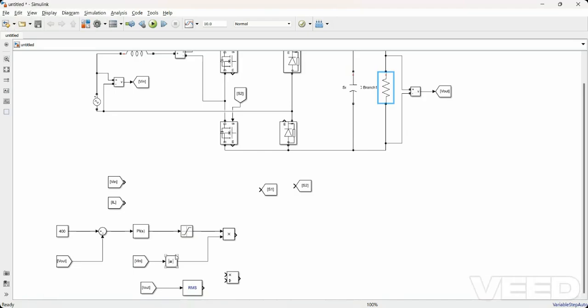So now it is important to have the volt ampere balance, as you can call it. VAC in multiplied by IL in this case must be equal to the V out multiplied by the I out. So you have to do a little bit of calculation. I'm just doing a quick one.